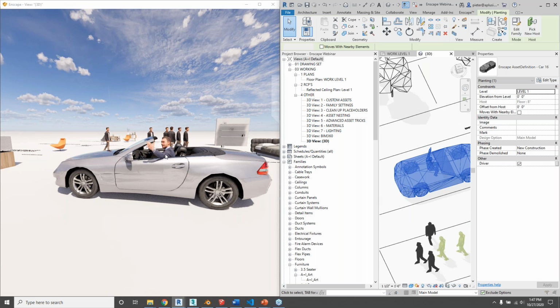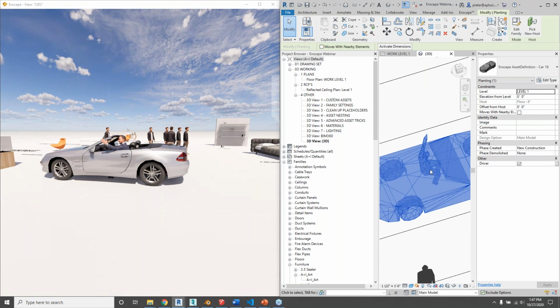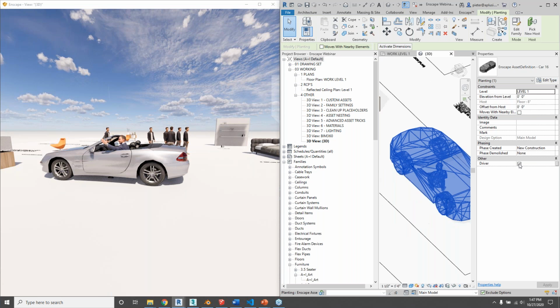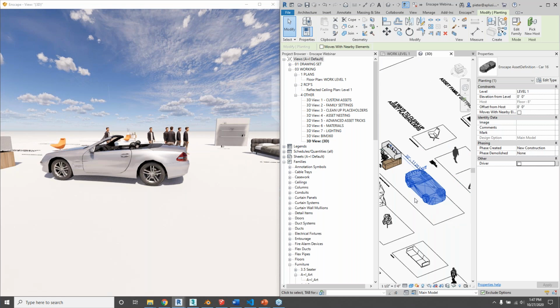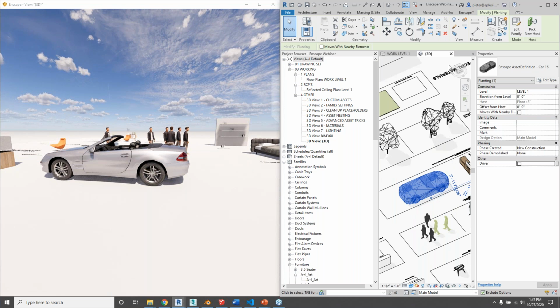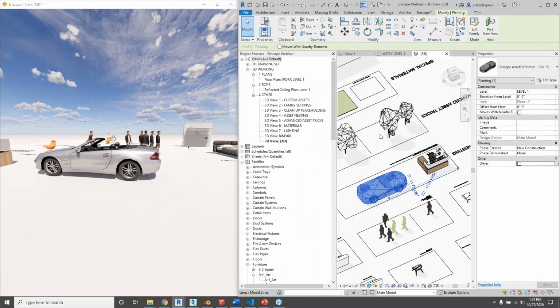And I also put a parameter on the nested family so that you can turn them off. So that removes the driver. And so that's a way, if you have assets that you find yourself combining all over the place, instead of grouping them, this is a more efficient way in terms of performance to do it.